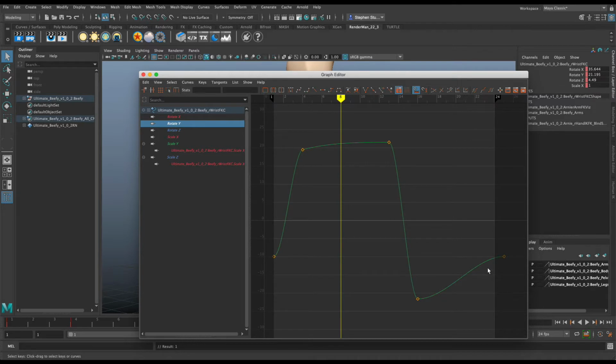And let's look at the Y. And again, I can do that. So I'm just kind of fixing these up a little bit. If you hit spline, it probably isn't going to work out because this angle doesn't match that angle. So I need to kind of adjust these so that they're sort of matching, right? Now, this might work out, or I could probably bring this down because this first key is lower than this second key, right? If you kind of look at that, and I'm going to kind of blend this just a little bit, right?